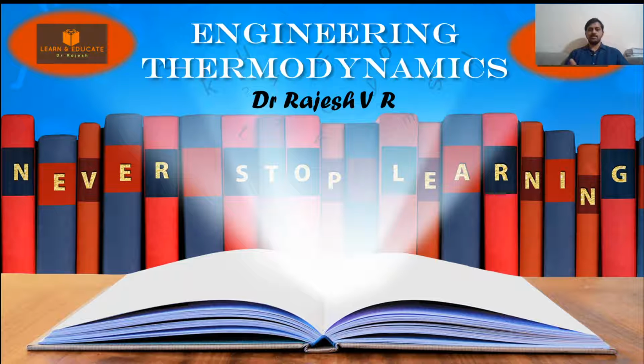We have studied what a system is, what properties are, what a change of state is, and what a process is. It is a change of state of a system from one equilibrium state to another equilibrium state. Right? Now, the importance of the quasi-static process in thermodynamics is that it is very easy to analyze. We will see the quasi-static process in detail. If you assume that a process is quasi-static, it will be quite helpful for us to analyze the problem easily. On the other hand, if it is a non-quasi-static process, we may have to put forth a lot of other assumptions, or a deep-rooted analysis might be required to study and analyze the problem.